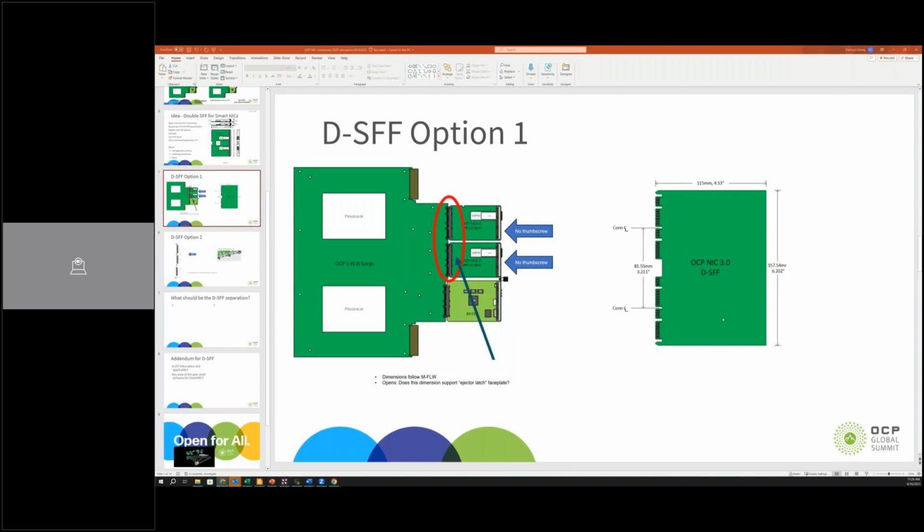Now, another thing is when you go to more advanced NIC solutions like what we call a DPU, or what our friends at Intel call an IPU, where you have a more elaborate SoC with DDRs, that's where an SFF definitely will not converge, even electrically. Just layout-wise, it will be very challenging, right? So that's where we have to go to either an LFF or this new DSFF.